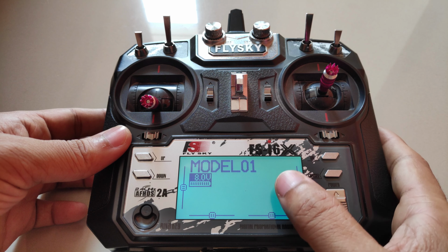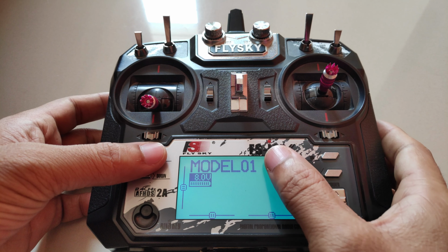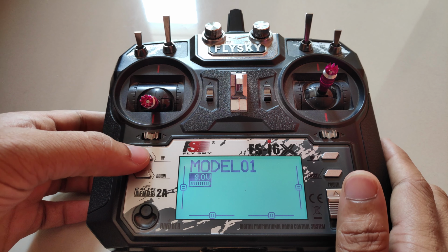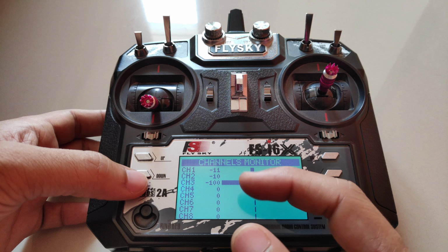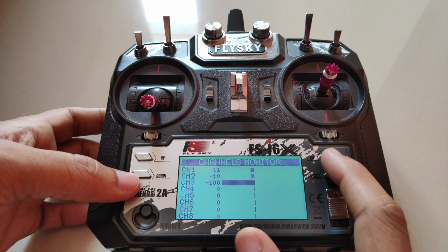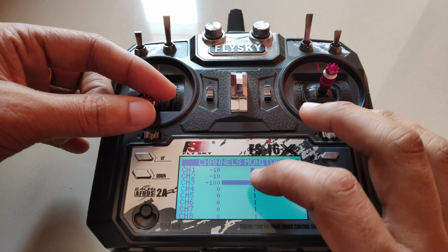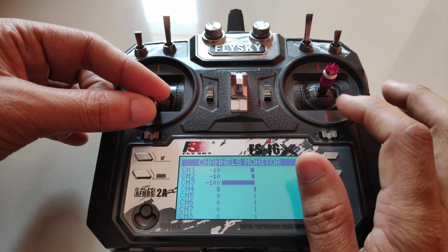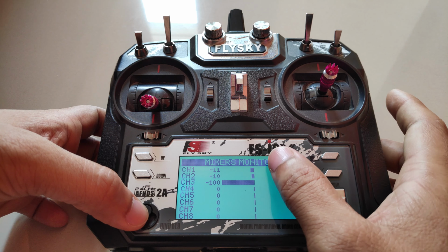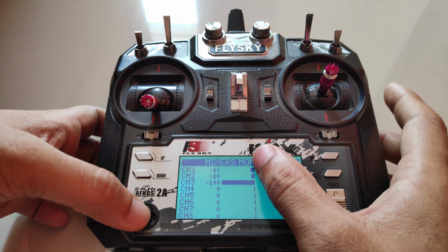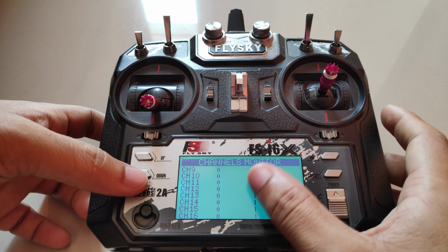Alright, so now that I have the latest version of OpenTX flashed on the radio transmitter, we can take a look at the new features and improvements. Firstly, if I navigate between the home screens, we have a new option called channel monitor and mixer monitor. In here we can see all the channels represented from -100 to +100 along with a slider representation. So you can simply navigate to this mixer and channel page within the home screen and then view all the channels.